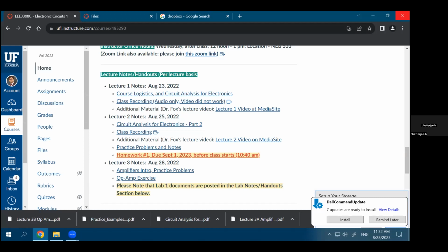When you think about the amplifier's function, to make it work there also needs to be a DC that sets the AC near this point. So effectively, this is a combination of DC and AC. The DC is basically this half VDD point, correct? And the AC is a small swing over that half VDD. The job of the amplifier is to amplify that small AC, but it needs a DC to make sure it can do what you want it to do.